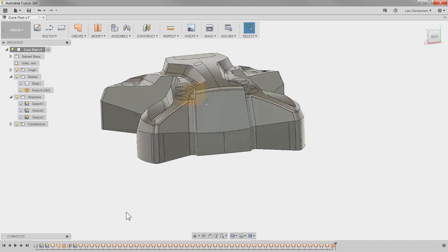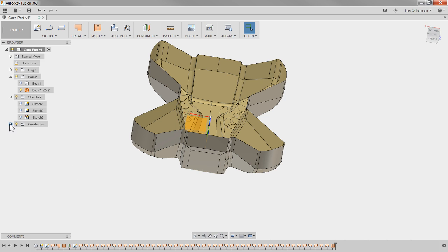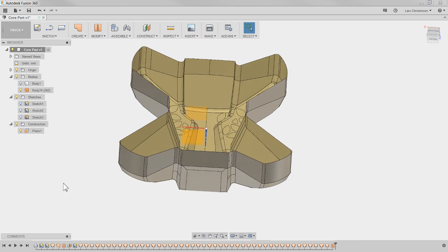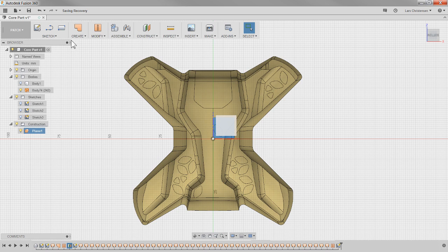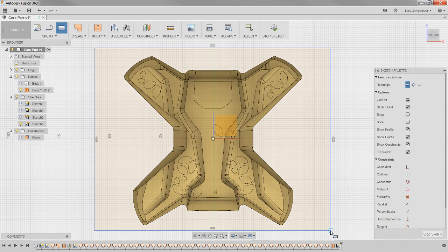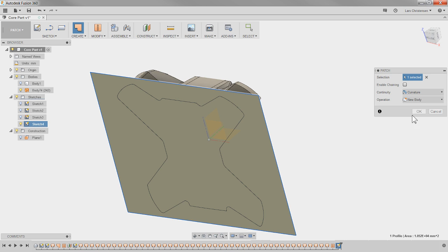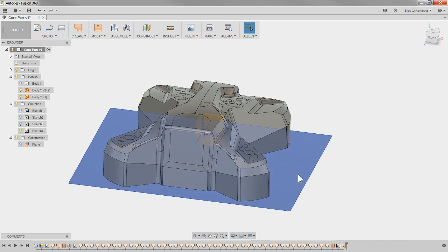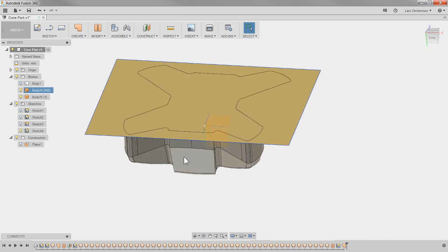What we're going to do last is we have to put the bottom in here. And again, there's different ways you can do that. I'm going to go ahead and open up another sketch on that 15 millimeter offset surface. And just to show you the trim command, I'm going to sketch a 2-point rectangle. I'm just going to make it bigger than the envelope here. So we got that, and then I'm going to patch that. Right? So now we kind of have that piece of paper sitting flush with our other one.